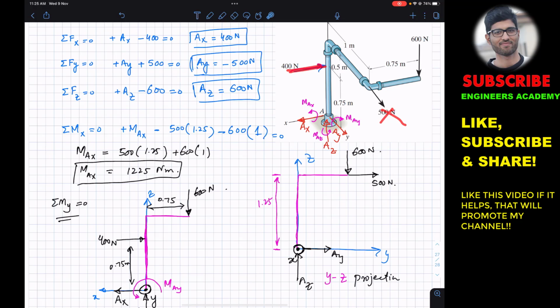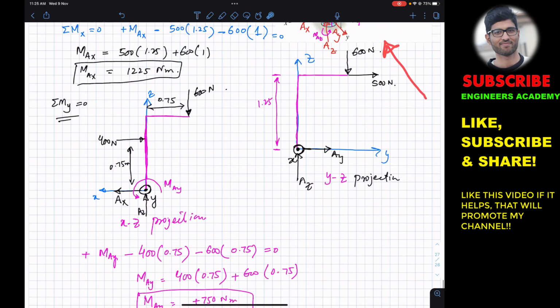This 400 Newton force is producing a moment about the y-axis in this direction. And if we curl our right-hand fingers in this direction, our thumb will point in the negative y. So that is why we are saying that this 400 Newton force is producing a clockwise moment about the y-axis if we observe the whole mechanism from this direction. So that is why we have a minus sign here.